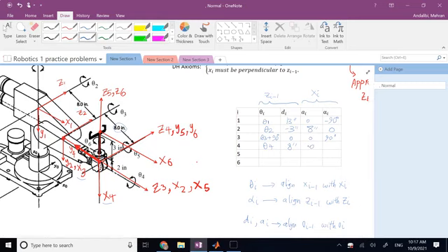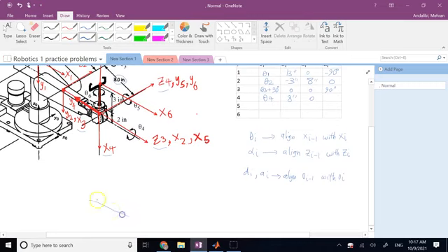And what about the z's? Are they aligned or not? Well, if you look, they are not. This is z3, this is z4. They are not aligned, and therefore you need to align them. So here again, I draw the shape for you. This is z4, this is z3, and x4 is downward like this, correct? And the rotation that you need is this much, 90 degrees.